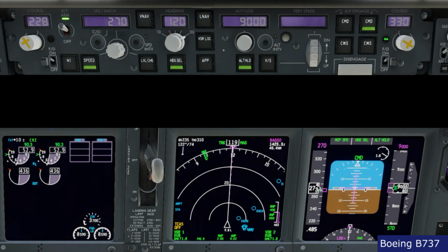Alright, let's see, for example, if I make an improper use of level change. So something that normally would be done with vertical speed, because I said vertical speed is for the finesse, for the small change of altitude. Let's say I want to climb to level 100. Now, as I press level change, we understand that level 100 is above our selected level and will go full thrust.